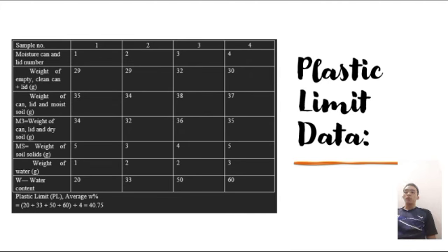As for the report, the liquid limit is 67%, the plastic limit is 41%, and the plasticity index is 26%.